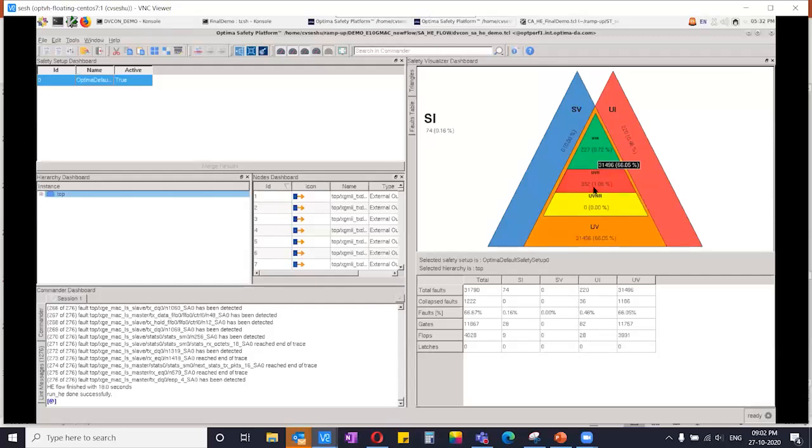If you remember how we mapped it, we can directly map this UVD into the safe scenarios, and then UVR is the residual where we need to take care. They're still dangerous because if a fault occurs, they are not really visible at the detection points, but they can still violate the safety goal. So in this way, you have to analyze all the fault flags and then try to improve the workload if needed, or try to improve the safety mechanism for some of the faults to be considered for the safety mechanism.